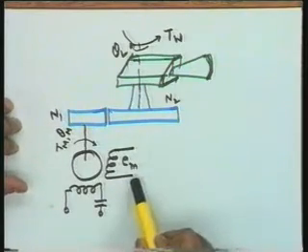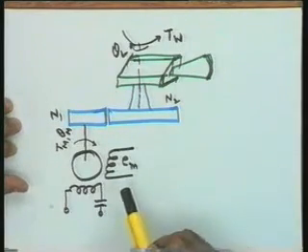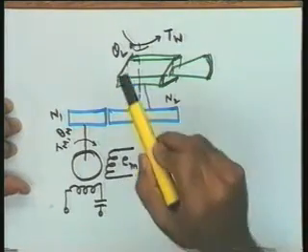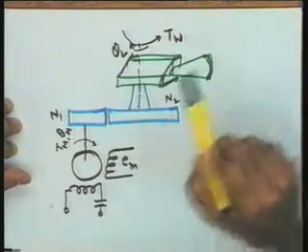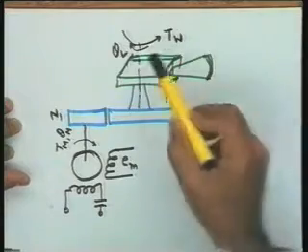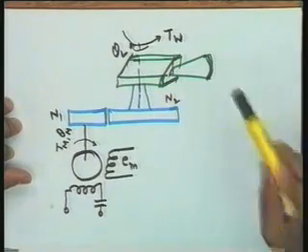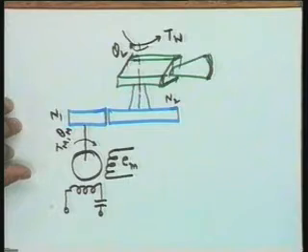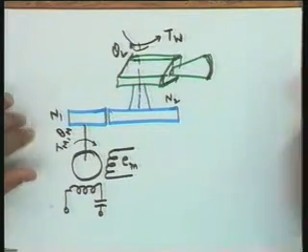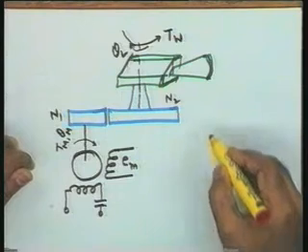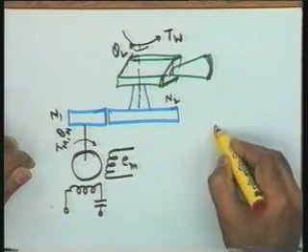This particular modulated signal should be proportional to the error between the commanded position and the actual position. The actual position of the camera is given by theta L. Now you require a commanded position. How do we give the command? Let me say that to this particular signal I give the command this way.